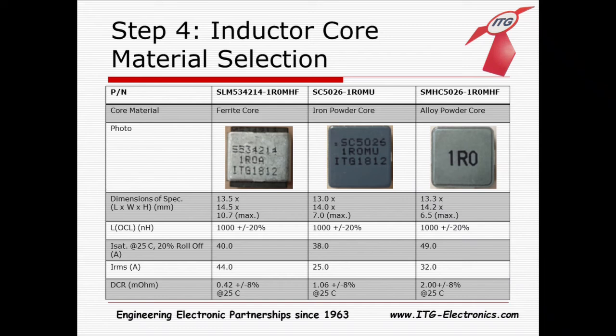So it's less of a concern and more appropriate for applications where you may be seeing an occasional surge in current, and you want to have some performance still from your inductor, but maybe you're not always going to be operating at that current, so you want to optimize the inductor's performance to something much lower with the ability to absorb a big spike. So that's where you would see a lot of the powder applications. And additionally, they can facilitate a much lower profile, a much lower height.